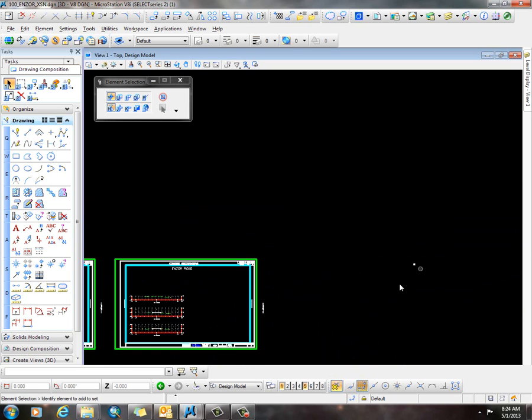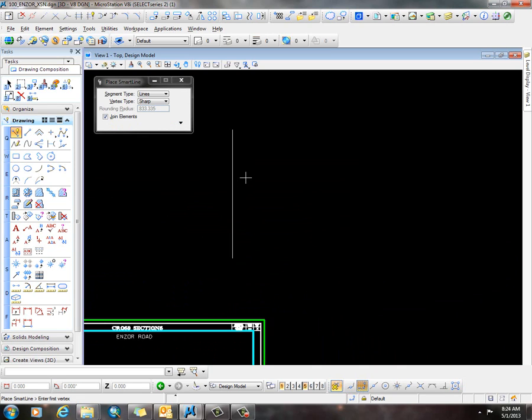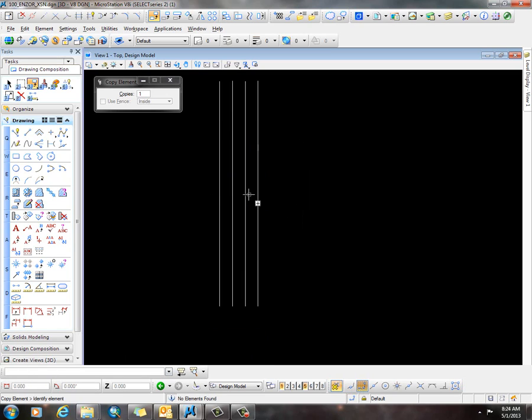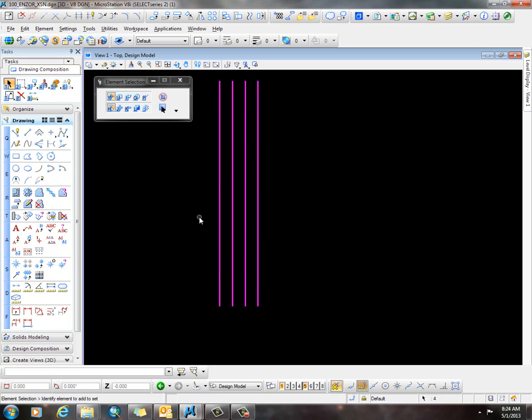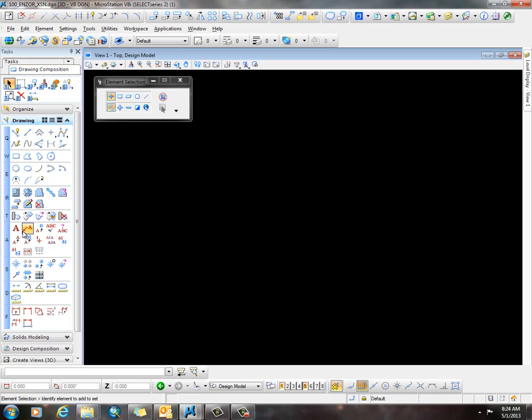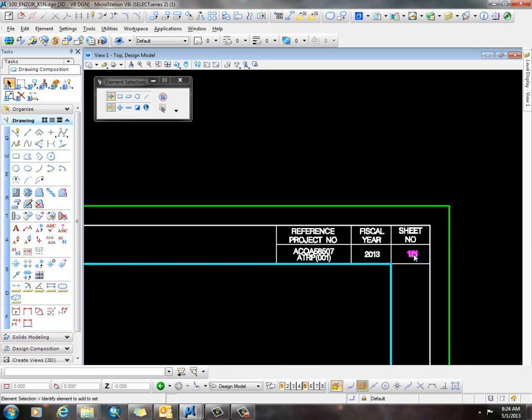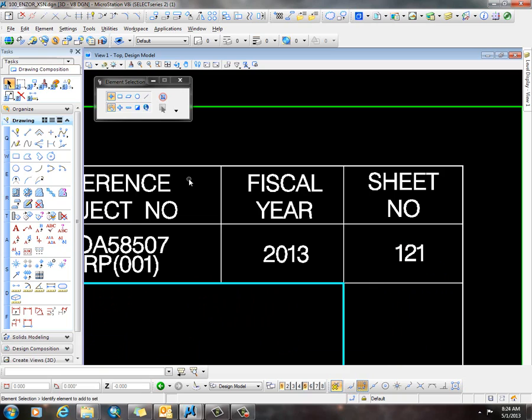You can utilize that command for copying. I want to copy this line, type in DX and say 10 to the right, none vertical, and 3 times, and hit enter, and it automatically does it. So the pipe just basically tells it to repeat the command X number of times. And that concludes this tutorial of some of the miscellaneous commands that are in MicroStation.